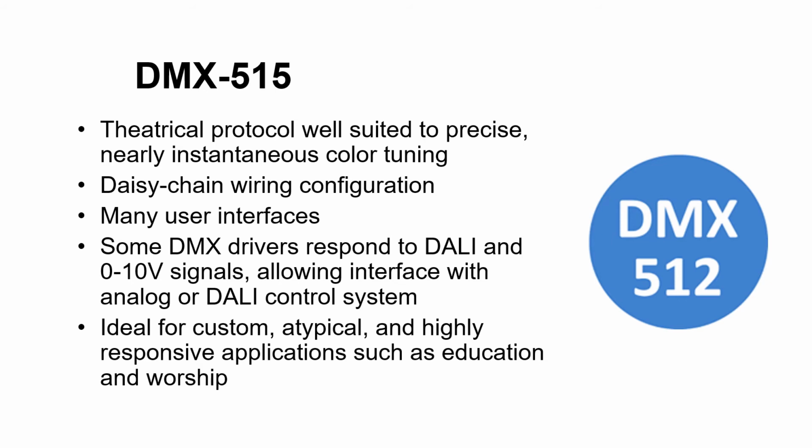Daisy-chained wiring is required, which means each device must be wired to the next in succession. A broad range of user interfaces is available, with color precision and repeatability being somewhat dependent on the interface chosen. DMX signals can also be used internally in Tunable White luminaires using multilingual drivers, even when the user interface is 0 to 10 volt, or DALI. This allows the Tunable White luminaire to respond very quickly while participating in a DALI system.